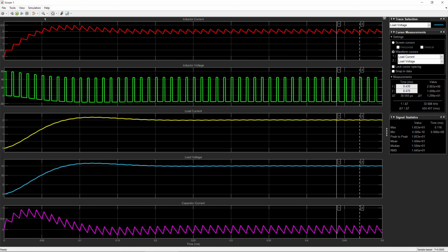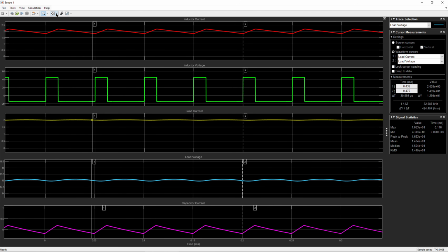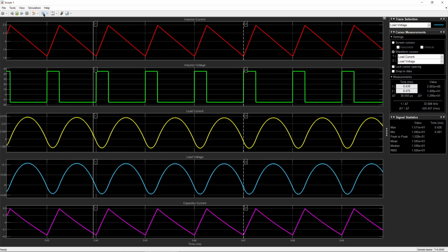We can zoom in on the output voltage here, so we can zoom in on this part. Let's do that, and then make this full screen in the vertical axis. So you see here exactly as we expected. We see some ripple at the output. You see here also from the inductor current, etc. So let's go first to the load voltage only, and then use the two labels and determine the peak value, and then compare that to the value we have, which is 0.15. That was the specification.